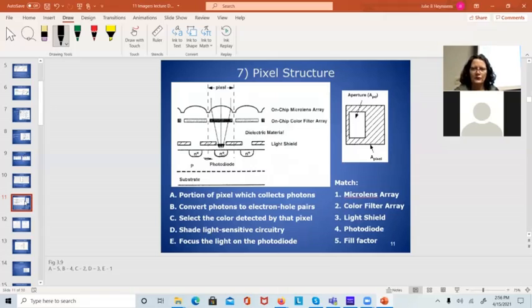So one of the figures of merit for this device is, if this is my aperture, this is the actual light collecting region. The stuff that's cross-hatched here is the readout electronics, and you have the total area of the pixel. So one of the figures of merit here is fill factor. What percentage of the pixel is actually light collecting?